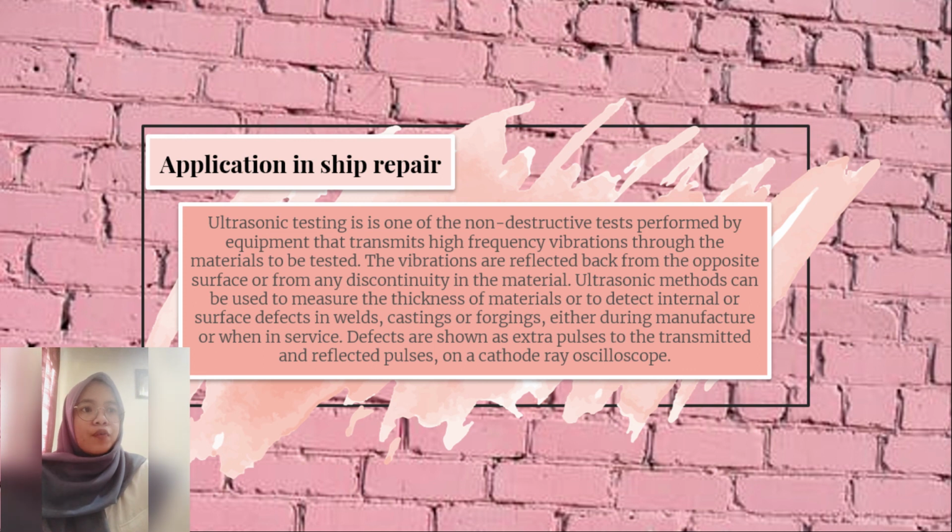The application of UT in the ship repair process. Ultrasonic testing is one of the non-destructive tests performed by equipment that transmits high-frequency vibration through the material to be tested. The vibrations are reflected back from the opposite surface or from any discontinuity in the material.